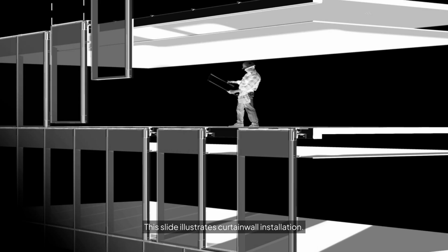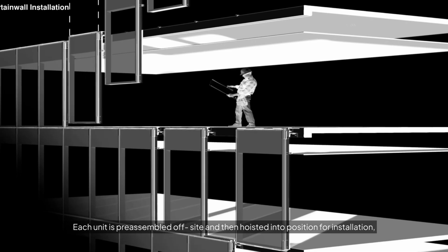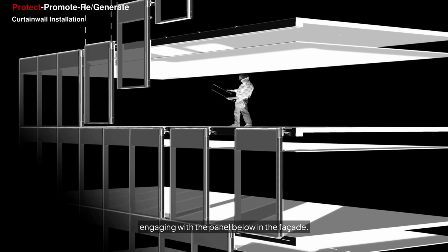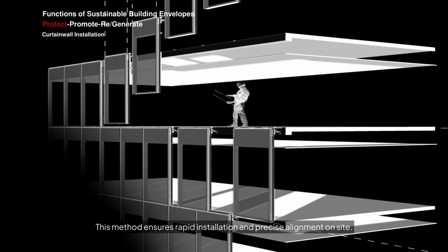This slide illustrates curtain wall installation. A construction worker guides a unitized curtain wall panel as it is lowered into place from above. Each unit is pre-assembled off-site and then hoisted into position for installation, engaging with the panel below in the facade. This method ensures rapid installation and precise alignment on site.